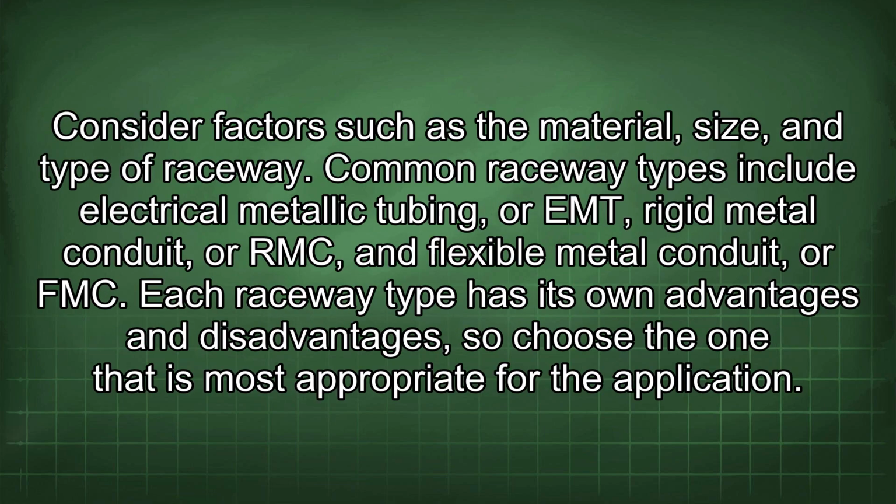Consider factors such as the material, size, and type of raceway. Common raceway types include electrical metallic tubing, or EMT, rigid metal conduit, or RMC, and flexible metal conduit, or FMC. Each raceway type has its own advantages and disadvantages, so choose the one that is most appropriate for the application.